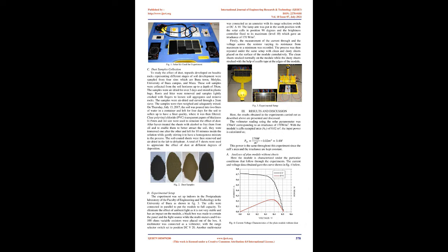Coupled with the module amongst others are a miniature 5 × 20 mm fuse link with a maximum current capacity of 1 A, mains connection, 230 VAC/50 Hz, a 12 V low voltage connection for the irradiation unit, a mains switch, position off counterclockwise rotation stop, and brightness control, scale 0 to 10, and a degree scale for solar module inclination and counter mark of the degree wheel.